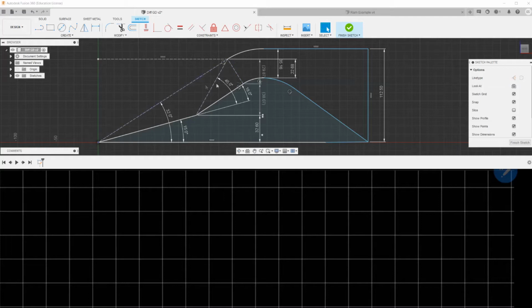This upper line here, which I draw, is the streamline that enters inside the diffuser. So the area of the entrance is constant, and the Mach number is constant, the density as well. So here we cannot influence the mass flow rate that enters inside the structure. When you are changing this size here, let's say the critical size inside the diffuser, in my case is 35.16, you are starting to constrain the subsonic part of the flow.